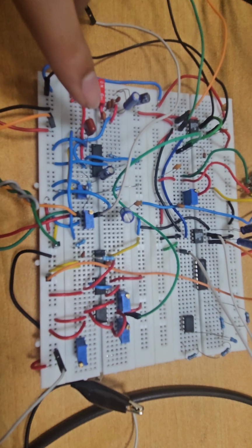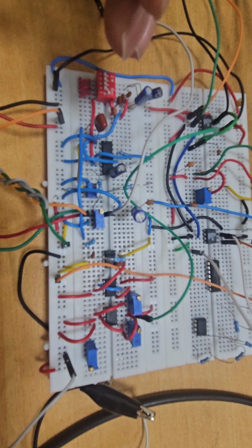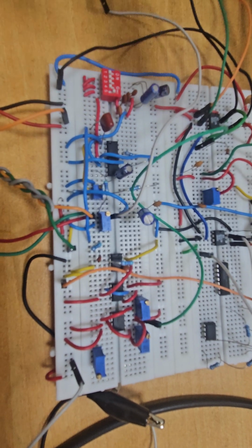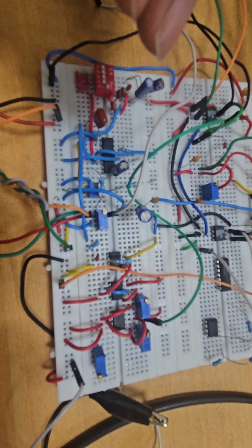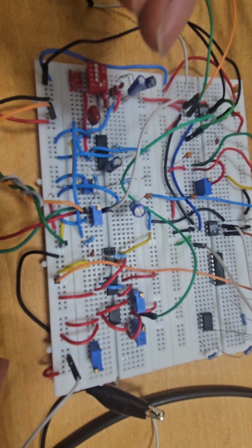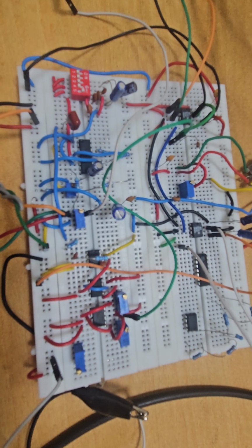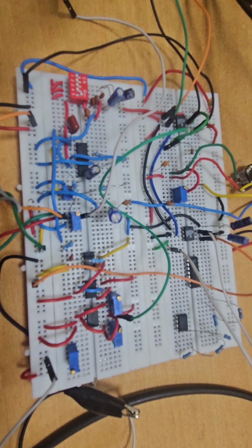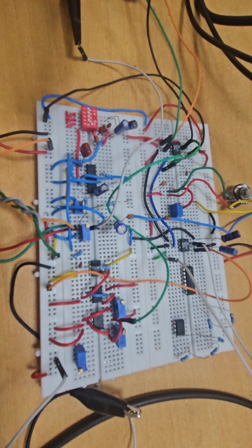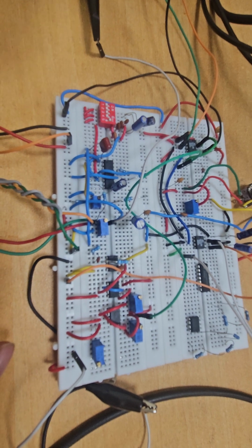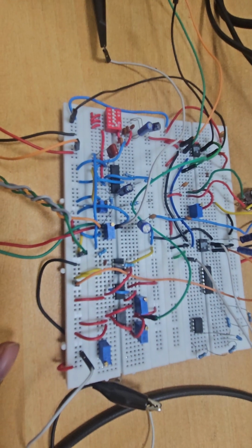Now if I want to demodulate that signal, I need to perform first differentiation, and then I need to perform the envelope detector, because when we differentiate our FM signal, which is nothing but cos of 2 pi fc t plus kf times integral of m(t), if I differentiate this signal, then the phase term will come out in the envelope part, which is nothing but 2 pi (fc plus kf m(t)). So my message came out in the envelope part of the differentiated FM signal.